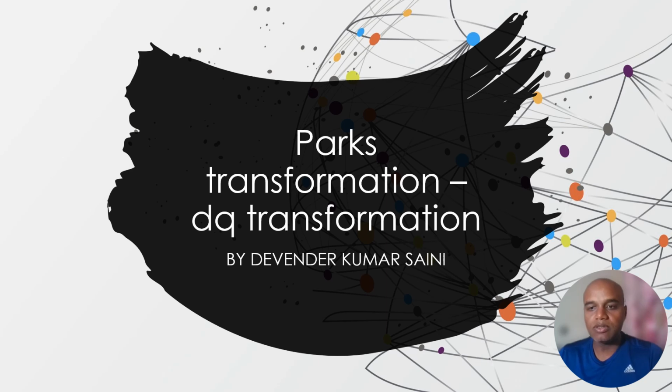These two reference frames, the ABC and the two-phase frame obtained from the Clark's transformation, are both stationary reference frames. Subsequently, the last transformation is done by using the Park's transformation, which converts those two phases into something like DC values, the direct axis and the quadrature axis. However, this frame is the rotating frame. So the first two frames are stationary and the third is rotating. This helps to control my AC motors very easily, and torque and flux can be controlled independently.